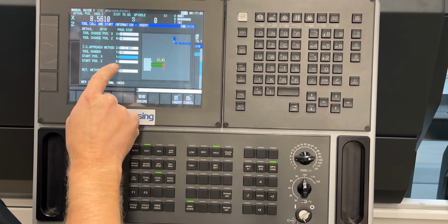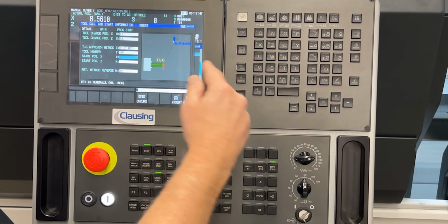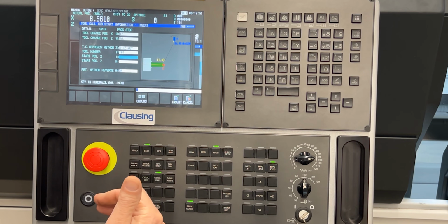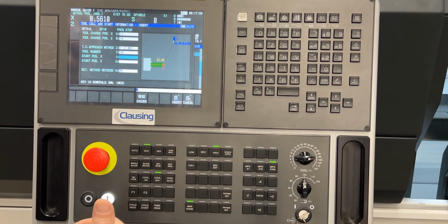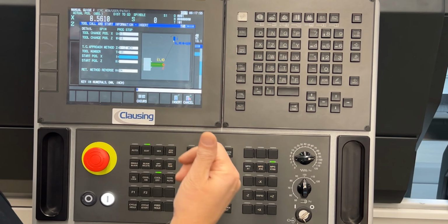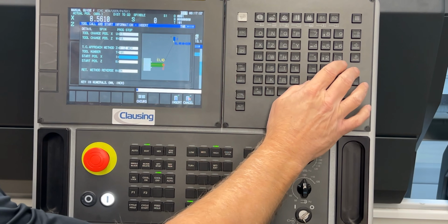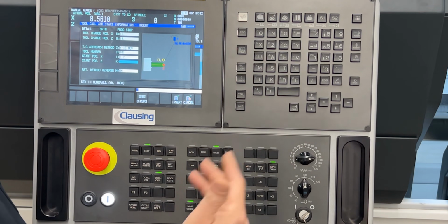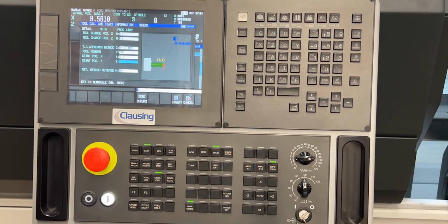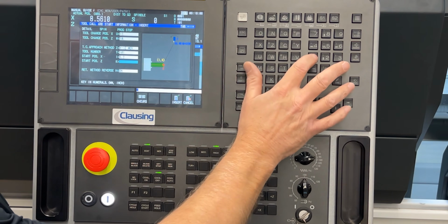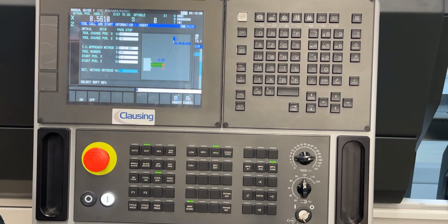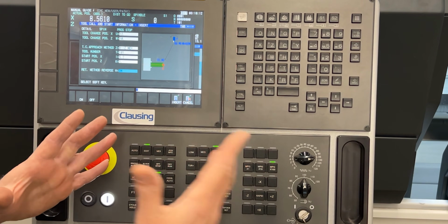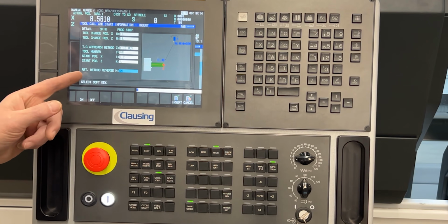The start position here is actually showing it coming back down toward the part. What is a good safe location on the approach to the piece? So I'm going to put in a start position of, let's say, 5.2, and we're going to assume that the part is 5-inch diameter, and a Z start position, we're just going to use Z of 1. The reason we're doing this is because the cycle itself will get it up closer to the part.